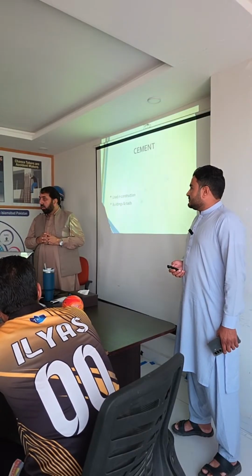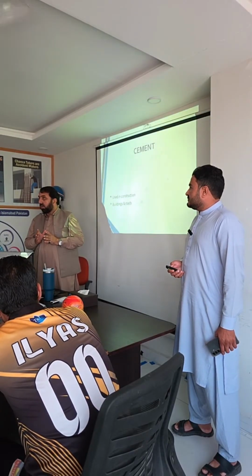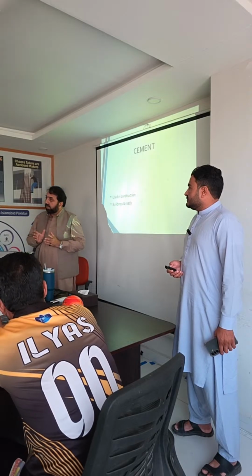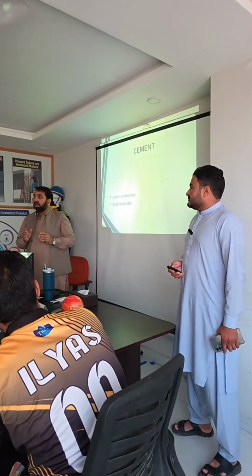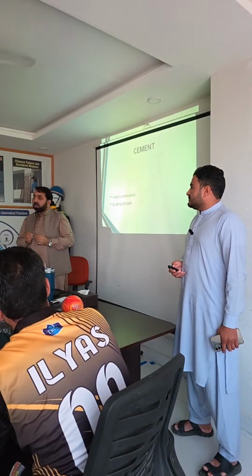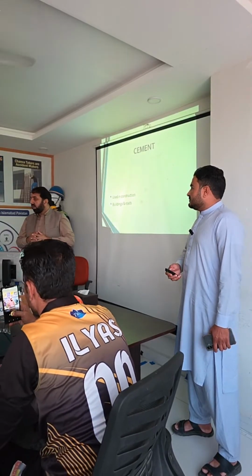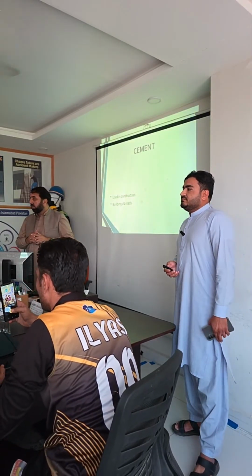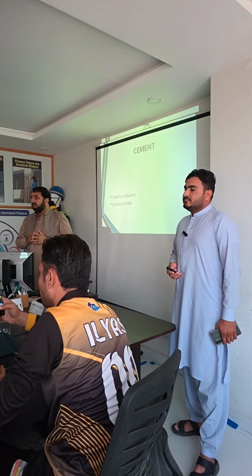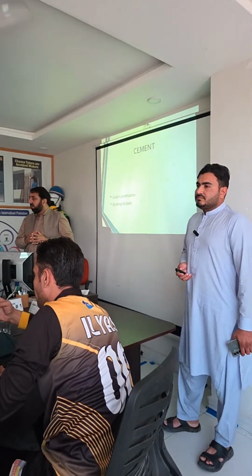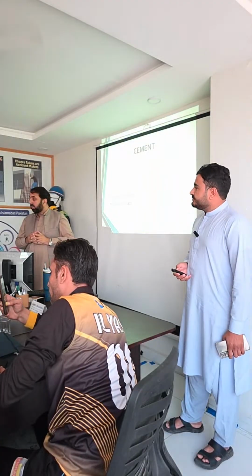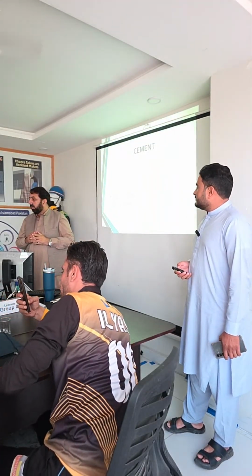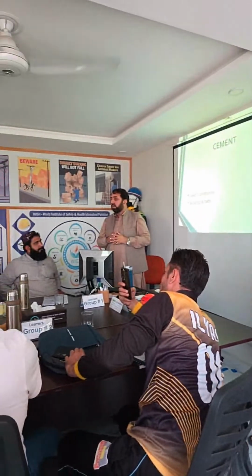So always look out for carbon monoxide. How can you detect it? I told you it cannot be detected by smell. So you must have a carbon monoxide detector in your workplace, like we have a fire detector. You install it, and if carbon monoxide is there, it will automatically alarm that carbon monoxide is now in high ppm. If a high ppm is there, you have to leave the area.